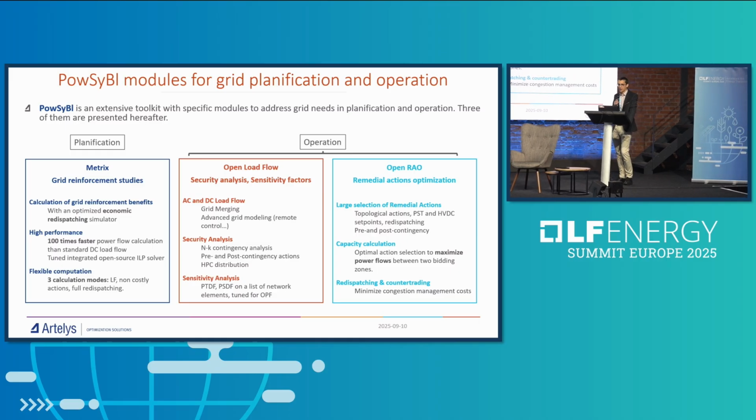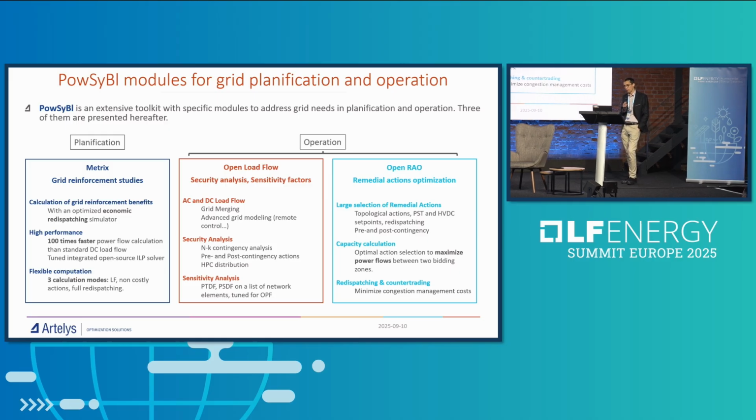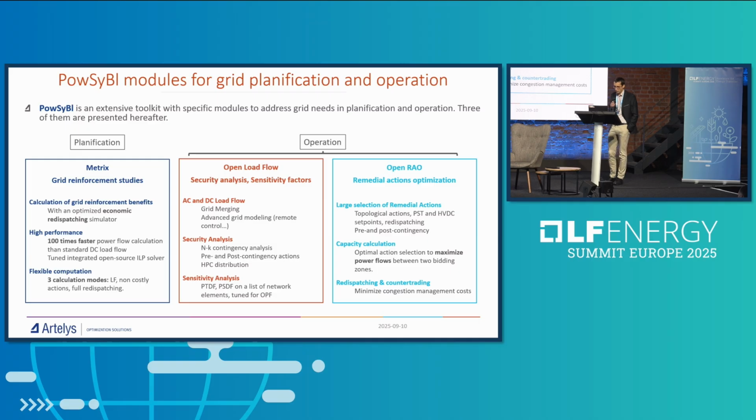It does a security analysis, N-K contingency analysis, pre and post contingency actions, and it's distributed over an HPC platform for scalability reasons. Last but not least, the sensitivity analysis: PTDFs, PSDFs, anything you need. Said like that, it does not seem that impressive, but if you don't have a good sensitivity analysis, you will never have a good security-constrained OPF. So this one was really developed and tuned to have optimization, and especially OpenRAO, in mind.